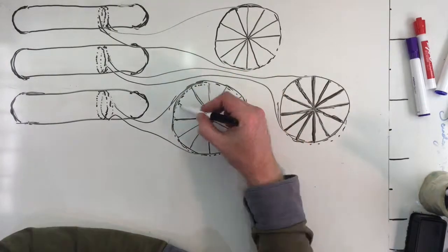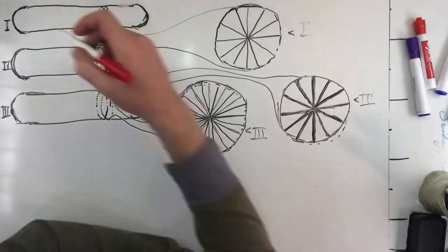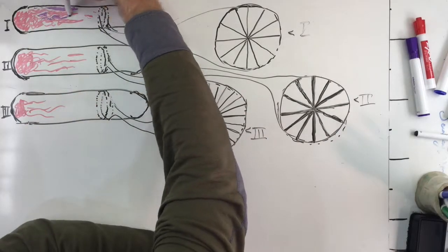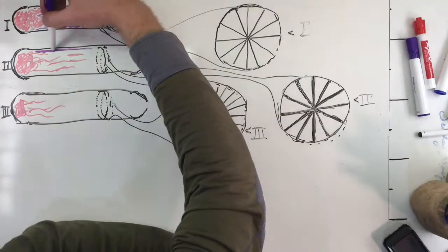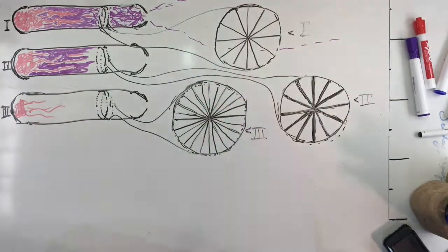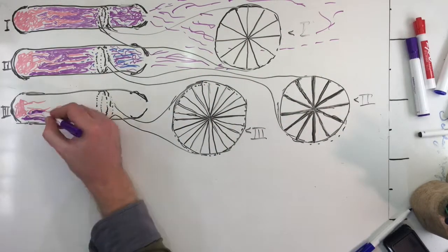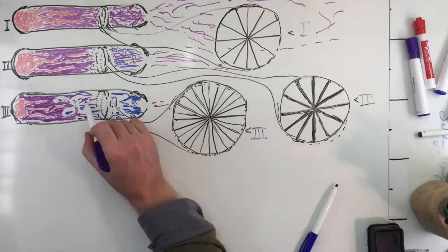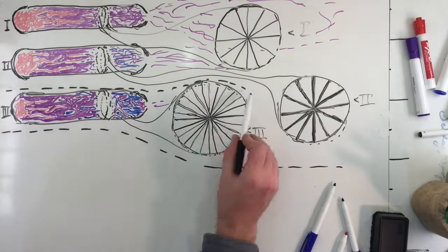The first has a set of 12 baffles extending radially out from the central shaft. The second does as well, but the baffles are twice as thick, so the larger coolant pipes that we can fit in them can absorb more heat as the steam passes over, and therefore they're able to condense more liquid water out of the vapor before it can escape out the back. The third has 24 baffles, all the same size as the first one. As a result of this, more coolant can circulate through this system as well, so it can absorb more heat than the first one could too.